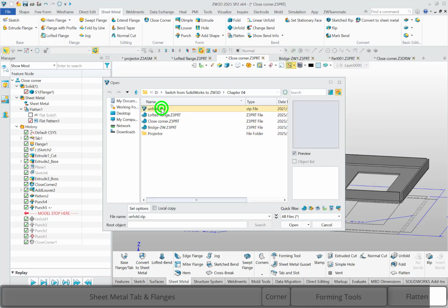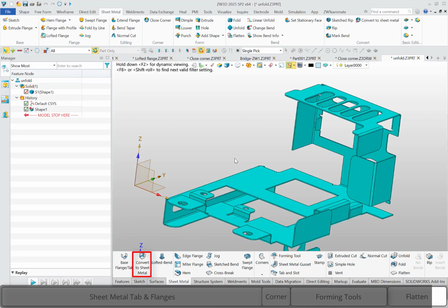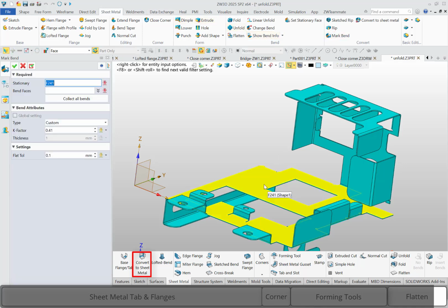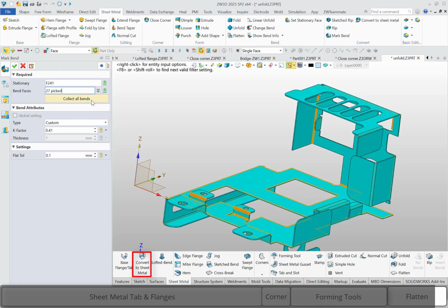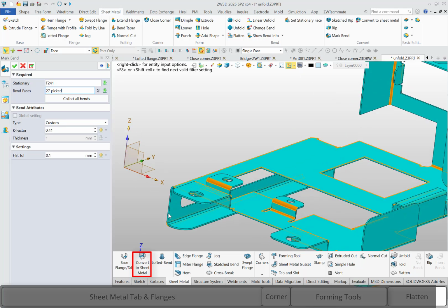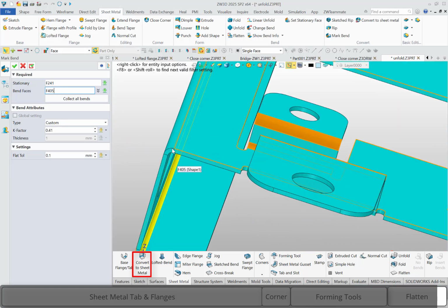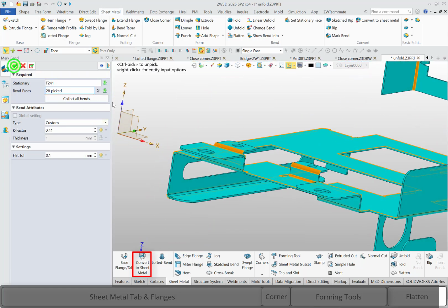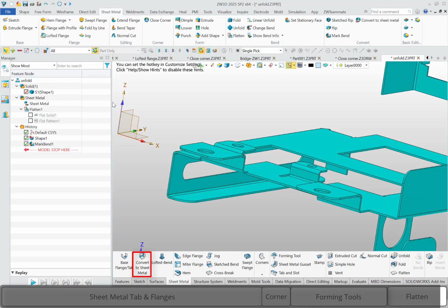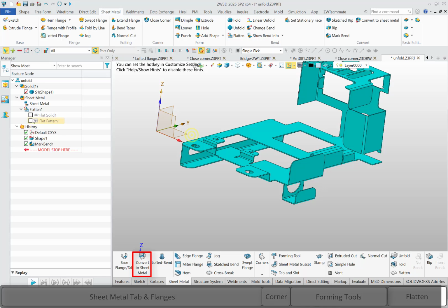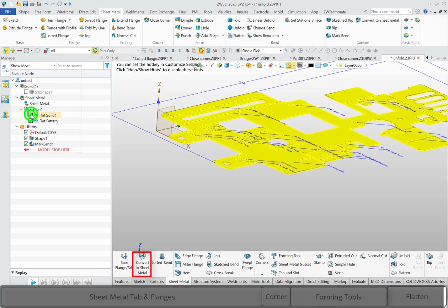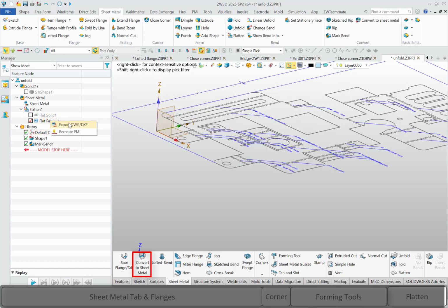After we import the sheet metal file, we can use the direct edit or healing to clean up the geometry. And we use the mark bend tool to detect bends and thickness. If some bends cannot be detected, you can edit manually. Here we have one. Okay, we can apply. Now it's already a sheet metal part. And you can see the flat pattern and the flat shape will be generated automatically. Then we can export the drawing as DWG or DXF as previously done.